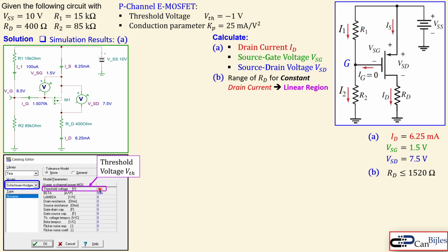So you can just type in yourself here, and then you make everything else zero to get close to the ideal condition. There's a beta, the SPICE parameter beta here, which is called the Kp in the actual SPICE parameter literature. But the Kp here is different than the K sub p.